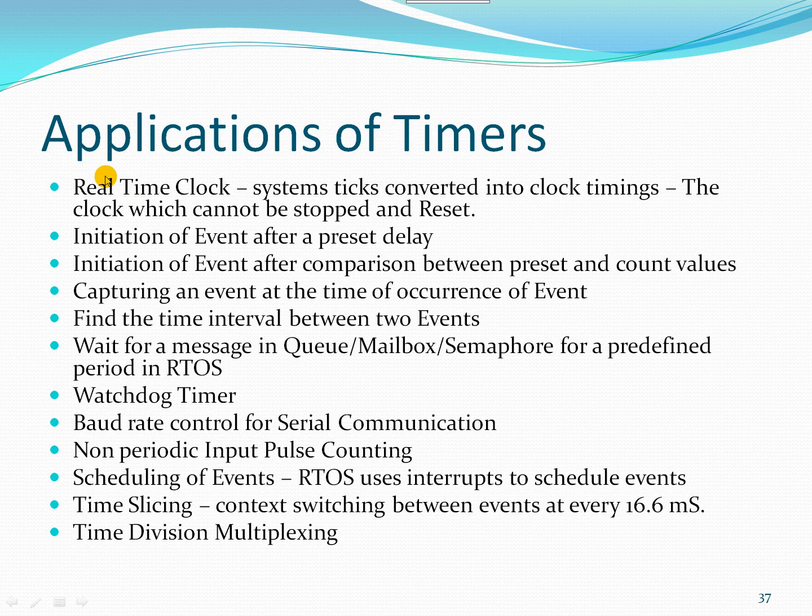Upon having 60 seconds of input clock pulses, they will be converted into 1 minute, and 60 minutes will be converted into hours, and so on. So we will have continuous counting of the clock pulses, and upon continuous counting, we will be updating into years also. Some of the real-time clock ICs may calculate the leap year also. So we can use those kinds of real-time clocks in embedded systems wherever we need that kind of control.